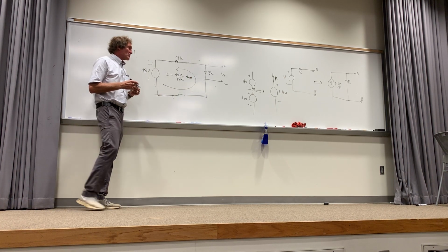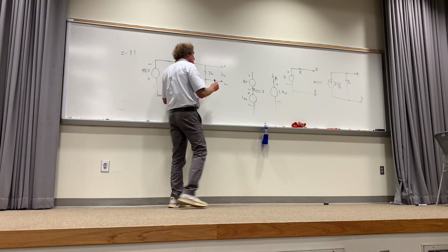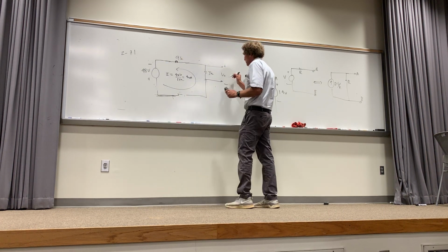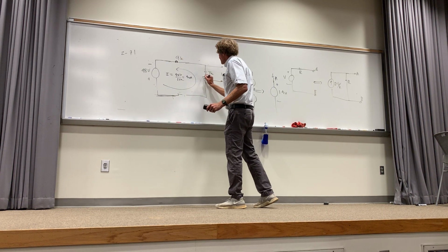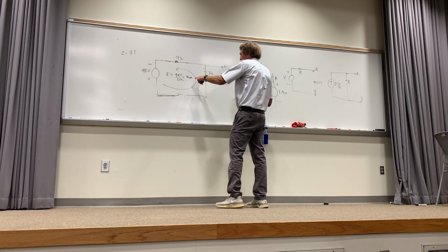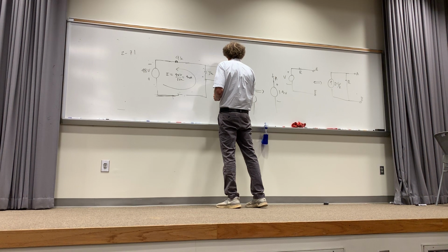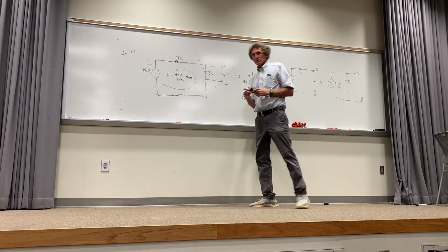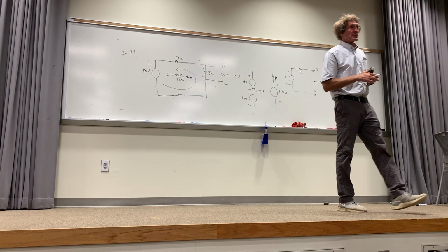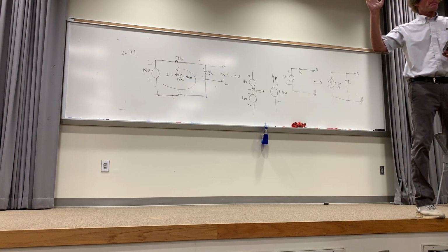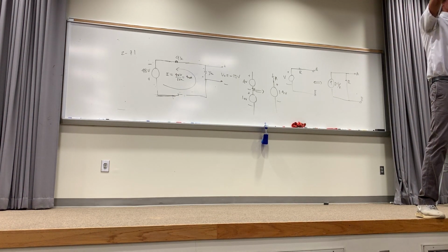And then if I wanted this voltage, well, the polarity is plus to minus. The actual voltage will be set up plus to minus, and it'll be 4 milliamps times 3K, or 12 volts, which means this voltage will be minus 12 volts. How many see this right here? Guys, you all see it? Who asked that? Does that answer your question?